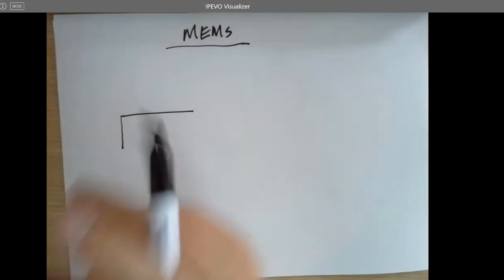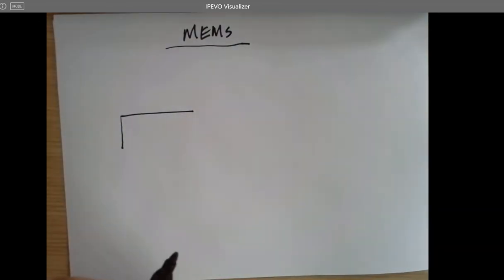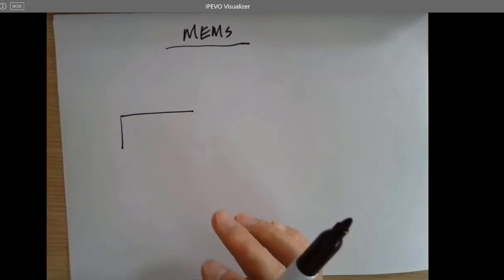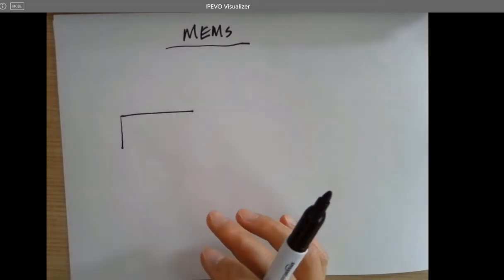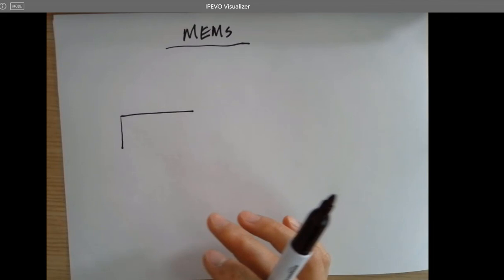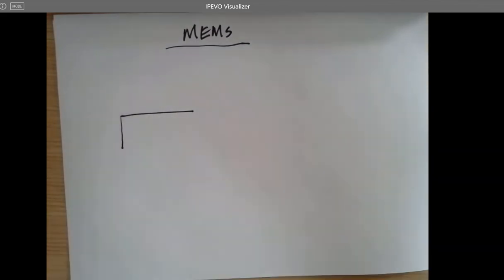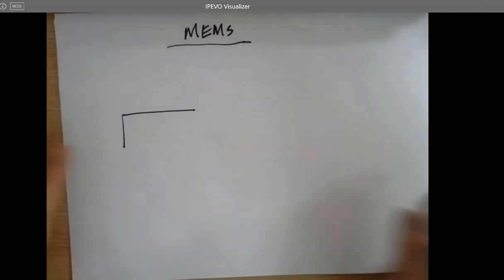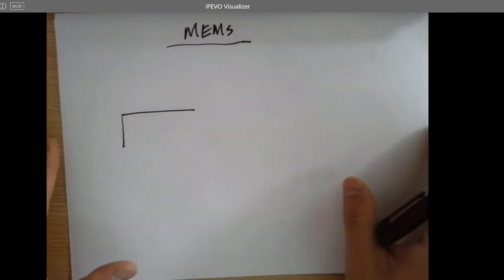The first MEMS device I developed in graduate school, I used electrical VLSI to draw it, but eventually I found out it's not really convenient, because electrical VLSI has all these shapes already designed for transistors and circuits, but not necessarily for arbitrary shapes. So I think AutoCAD is way better when you're designing MEMS devices.